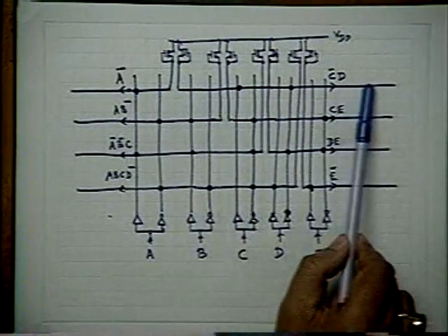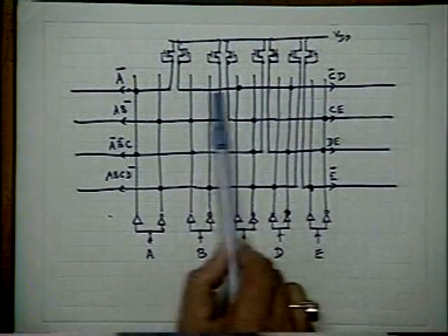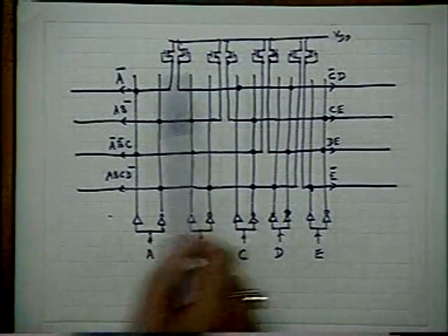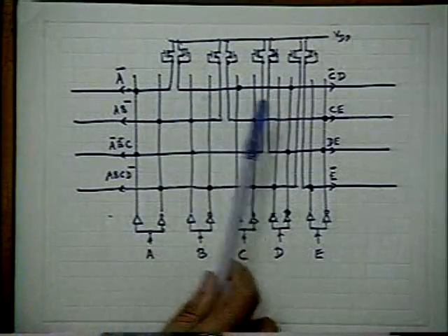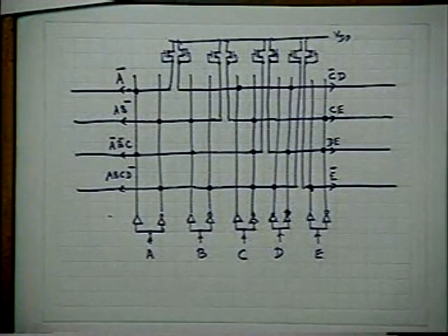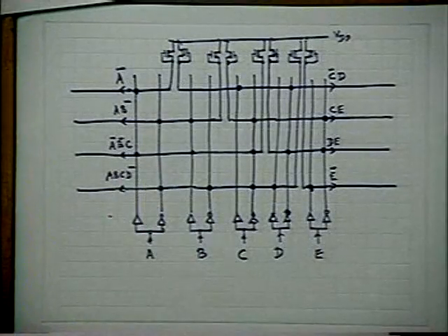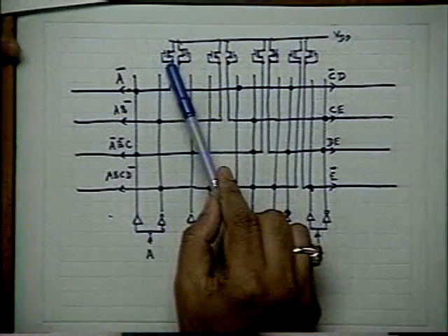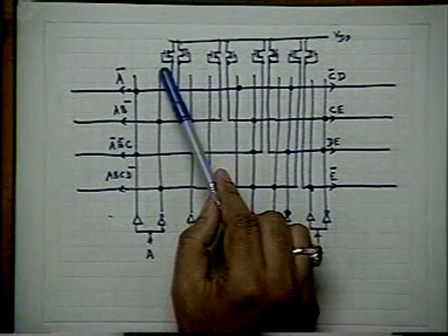This is a load transistor for this inverter, this NOR gate. But this is the load transistor for the earlier case. Earlier, all the load transistors of the different inverters or NOR gates were shown at the left, but I cannot do that now because the left and right sides will be utilized for realizing the two OR planes. So I have to split the transistor row somewhere and go vertically up or down, whatever is convenient, and place the corresponding load transistors.